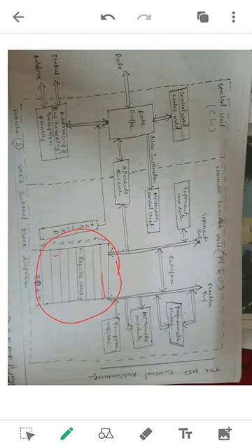There are two operations called push and pop. In the 8087 it has a 3-bit pointer which holds the number of the register that is the current top of stack. When the 8087 is initialized, the stack pointer points to 000, and register 0 is top of stack.